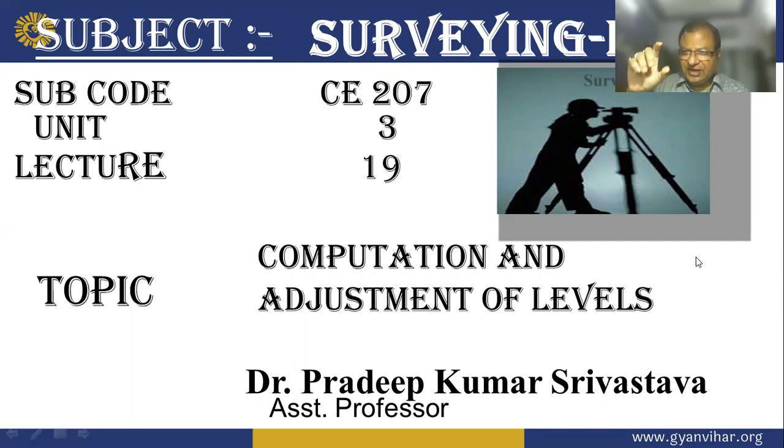Entire one page, this is the rule of survey, when it has been filled and completed, then you will find out the RL and the differences, and compute all the data. Total backsight minus total foresight is equal to the first RL minus the last RL. This is computation.